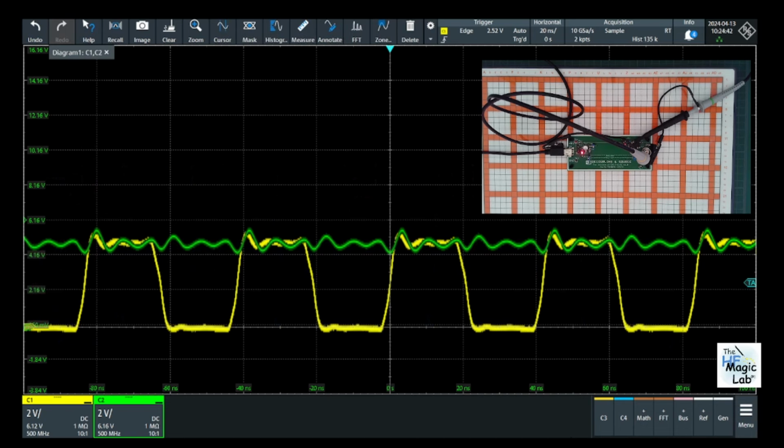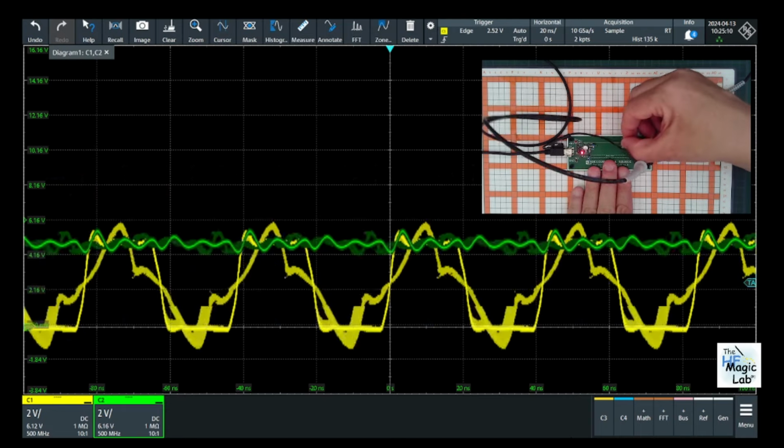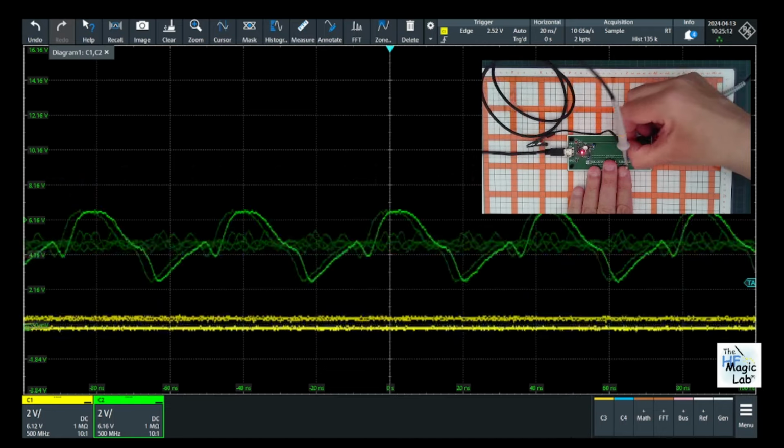So as I explained before, this is a typical solution for the signal and power integrity worlds. Remember that I am using pigtails, so the signal is totally clear, and because I am using jumpers, the inductance of my decoupling network is not optimized. But how is the effect of this decoupling network in EMI? To do this, let me deactivate the decoupling capacitor again.